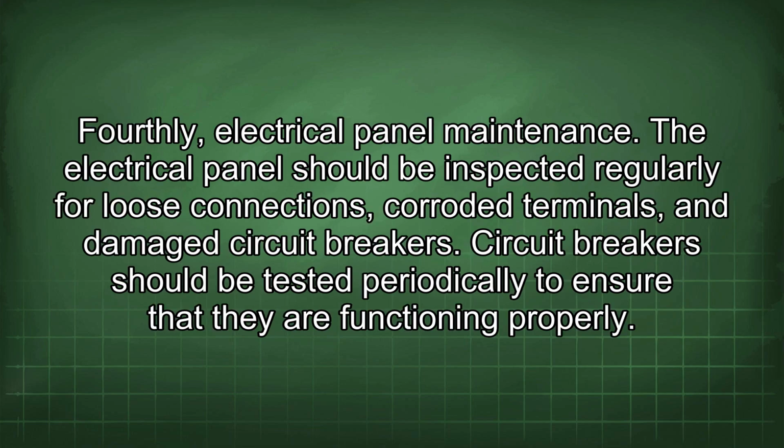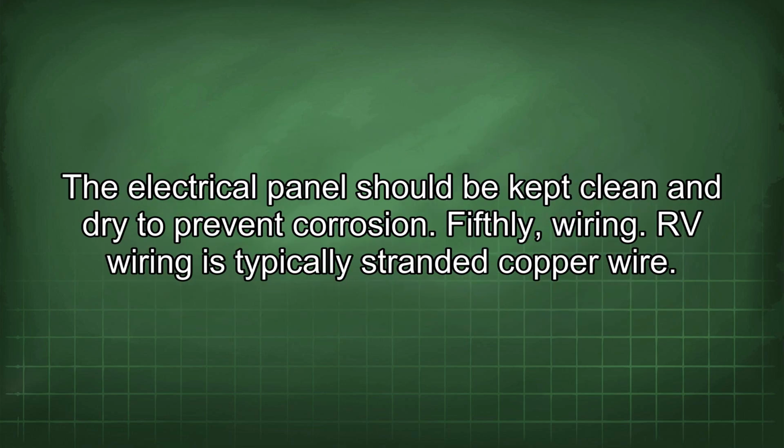Fourthly, electrical panel maintenance. The electrical panel should be inspected regularly for loose connections, corroded terminals, and damaged circuit breakers. Circuit breakers should be tested periodically to ensure that they are functioning properly. The electrical panel should be kept clean and dry to prevent corrosion. Fifthly, wiring.